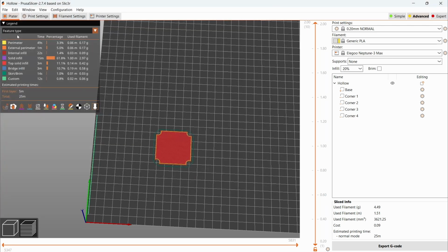While saving the project is always a good idea in case you need to make changes later, we also need to export the model to an OBJ file. This is because if we try to use the 3MF file as our negative volume, the 4 corners would be lost, as PrusaSlicer doesn't seem to support negative volumes within other negative volumes.